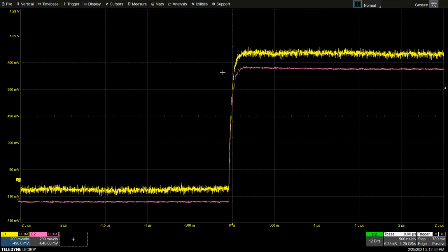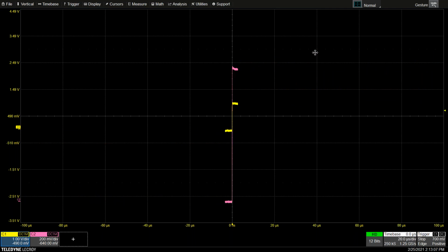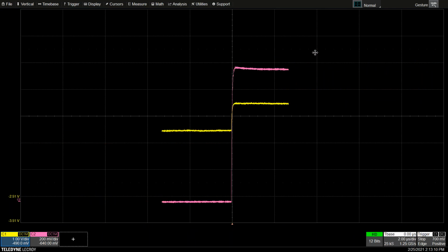And it's even worse if you folks are using an 8-bit scope. So instead of 256, a quarter of that, 64, you've made your 8-bit scope a 6-bit scope. So the amplitude measurements from your display, by shrinking it, with the purpose of today's webinar, coffee break, is to really, if you're not really trying to make accurate amplitude measurements, then shrinking the waveform is just absolutely fine, right? There's no problem, and you'll be able to capture that.